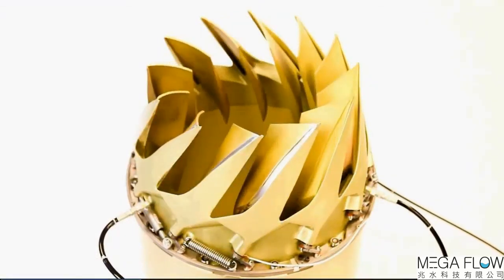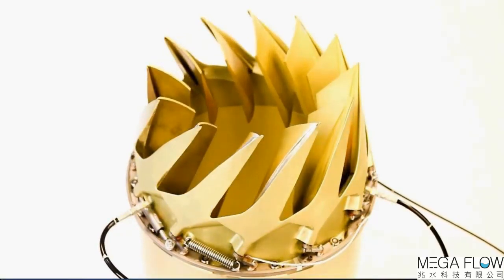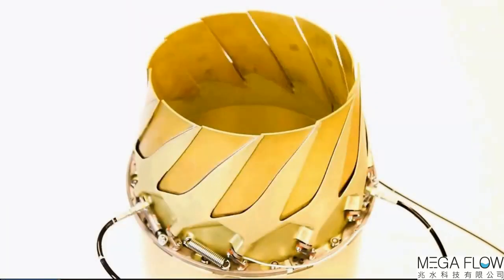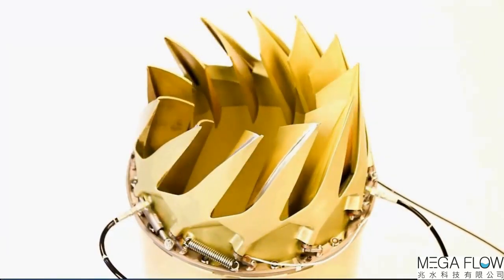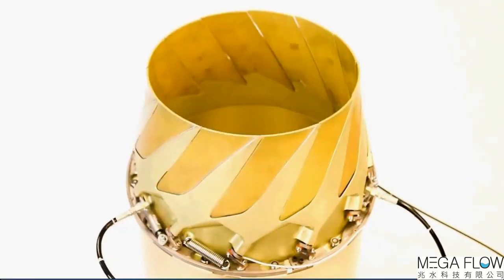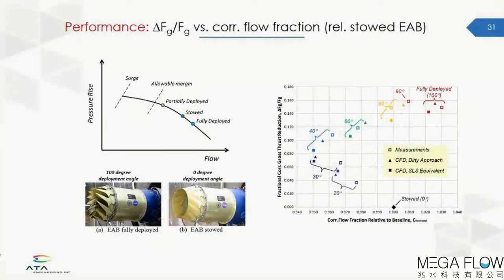As you can see, we've got these single acting rams which get hydraulic pressure. They rotate a ring. That rotates the vane shafts via a lever arm, which is connected to an adjustable linkage. And those vanes are acting against a spring, and that spring was there as a safety feature so that if hydraulic power was lost, these vanes would return to the stowed position. Generally in operation, the spring is greatly assisted by the engine's aerodynamics as well, which want to force these vanes to close.